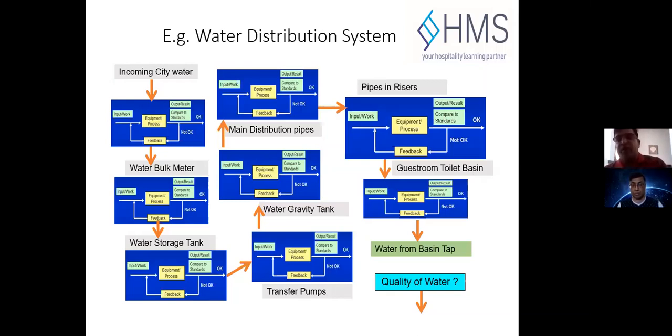Like once we talk about the hot water, as we previously mentioned, we need to maintain 48-degree temperature in the guest room. To maintain the 48-degree temperature, we need to see what temperature we are maintaining in our storage tank. Okay, and then what is the insulation we need to have on our pipe, so at least we don't lose the temperature from distribution.